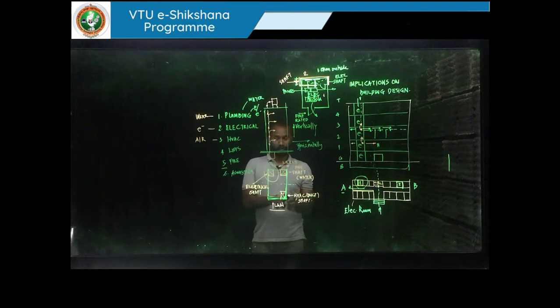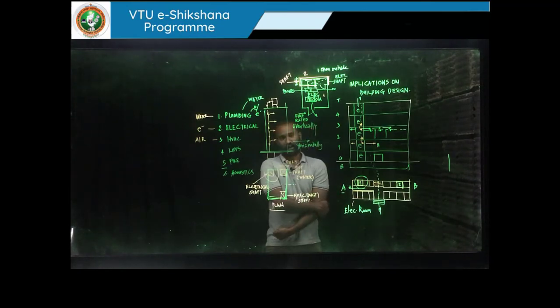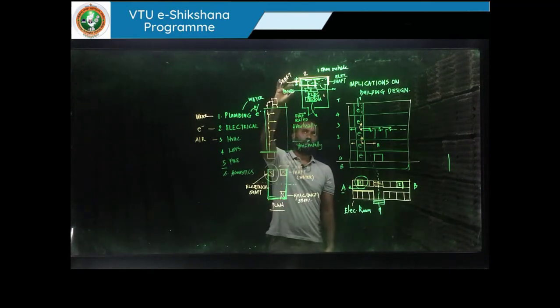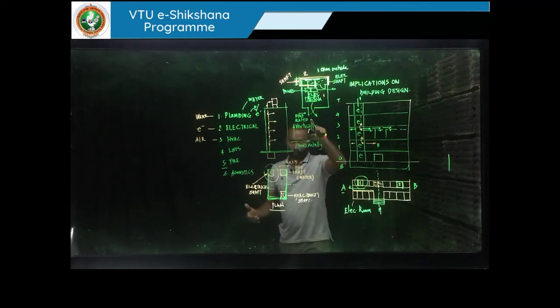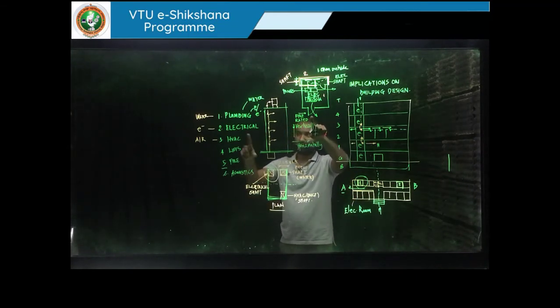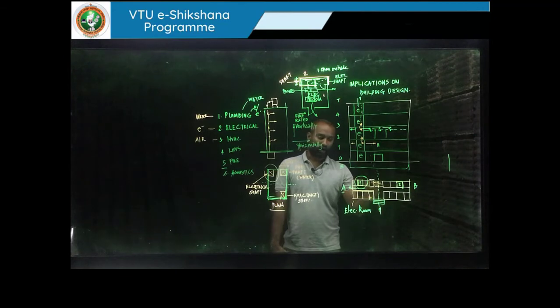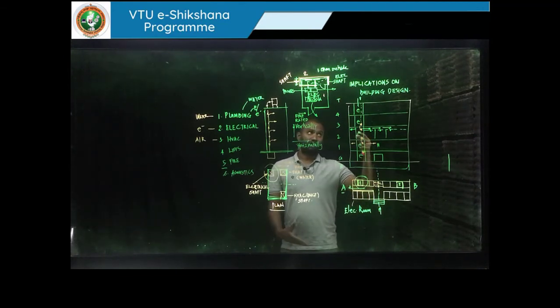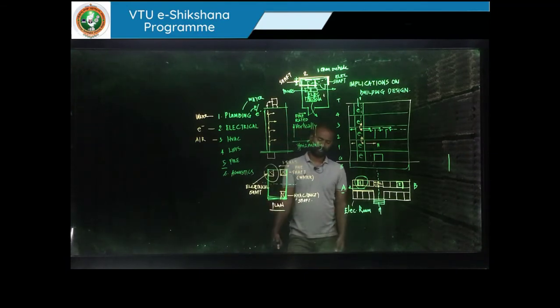So by doing this, you are eliminating so many other problems, which will enable you to focus on the design aspect of it, the aesthetic and architectural part of your designs. So retain the shaft, plan your shaft location, and plan your electrical rooms and which side they are going to come. Make sure your door opens outside, at least for all the services rooms, right? So this is how the design is going to be impacted by your planning of electrical services, or for that matter any services.